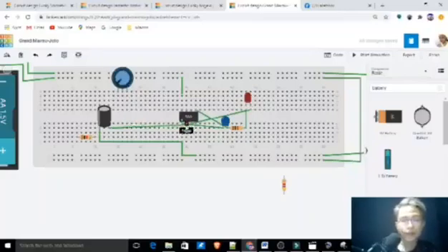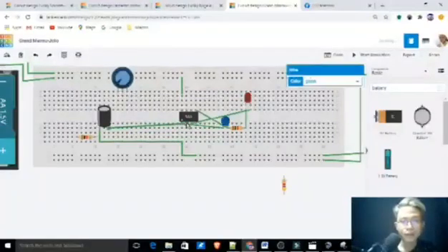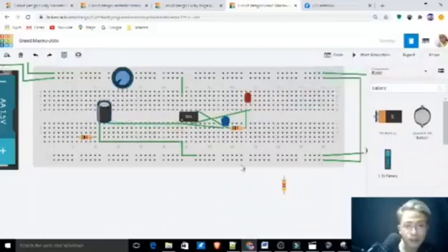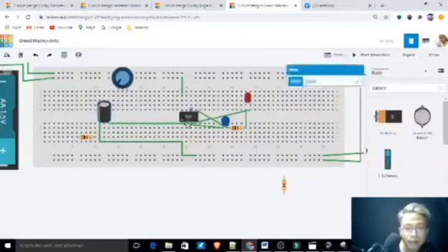And we have to connect that one into the pin 6. So I think it's a little bit confusing if we remove that one here. Okay, so here we have to connect to this pin 6. Okay, we connect our pin 6 to the pin 2.